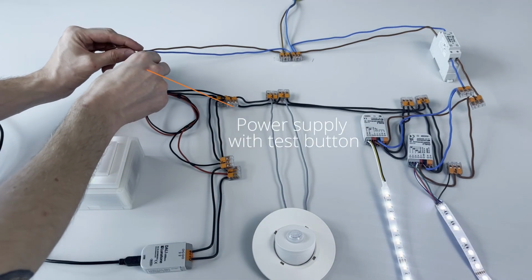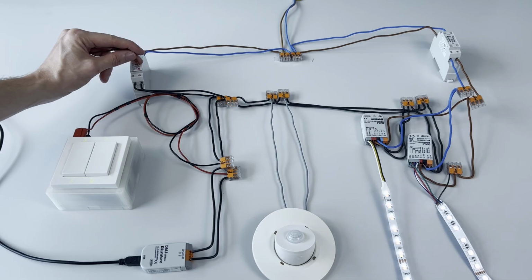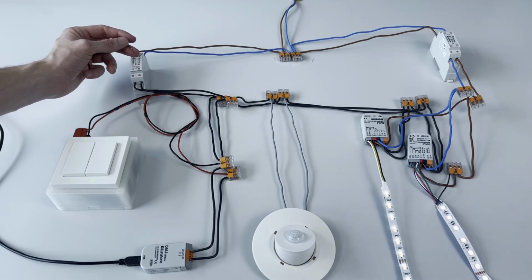If your DALI 2 power supply has a test button, once all devices are connected, you can check the wiring is correct with the test button. A short press will send a broadcast on command. Pressing again will send a broadcast off command. A long press will start the testing pattern of on, off, then dimming. The pattern will stop when any other DALI command is sent on the DALI line, or with another short press of the test button.